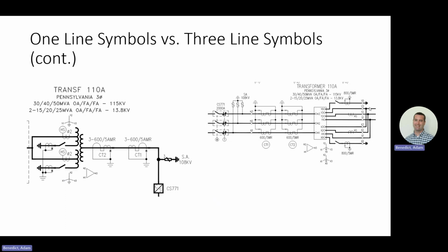Let's see, moving down, you see our secondary connections line up, and basically all these connections need to match, right? That's the whole goal. Every time you're checking a drawing, whether it's a one line or a schematic or wiring, you should be checking against something, right? What's your basis for doing this? You're not doing any one of these drawings in a vacuum.